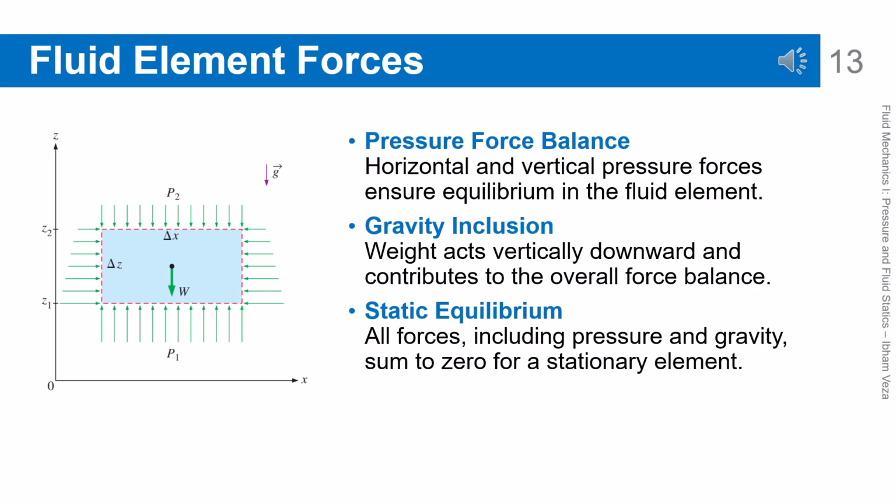Fluid element forces. A fluid element is subjected to pressure forces on all sides, and its weight acting downward. For a static condition, the sum of all forces must be zero. This equilibrium applies in both horizontal and vertical directions. From this, the relation between pressure change and depth can be derived. This principle is the foundation of the hydrostatic equation.